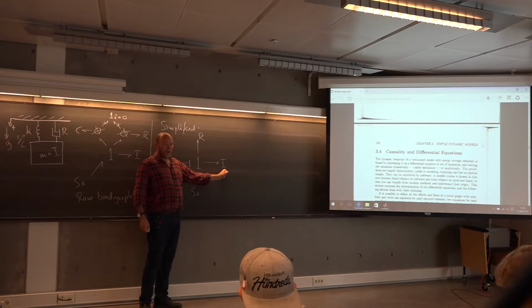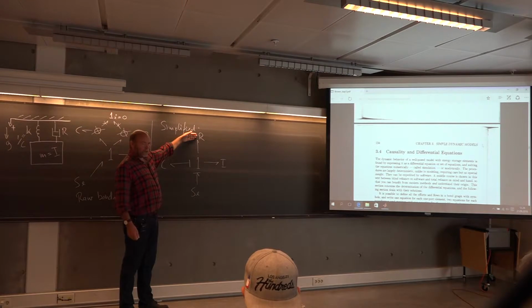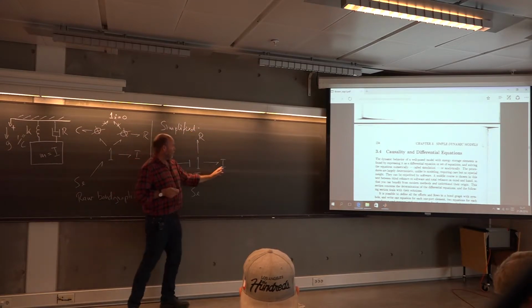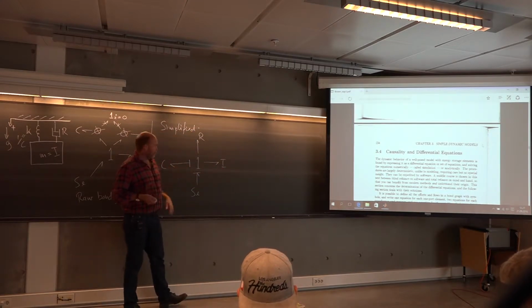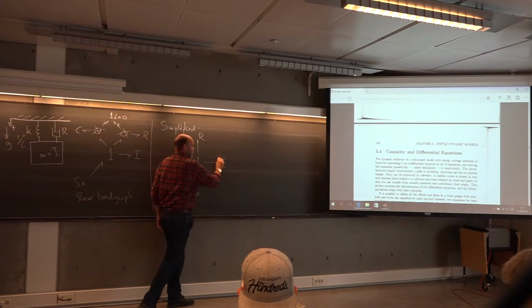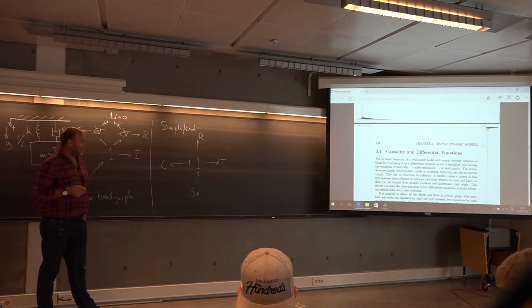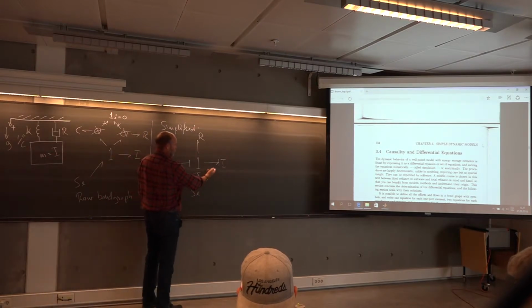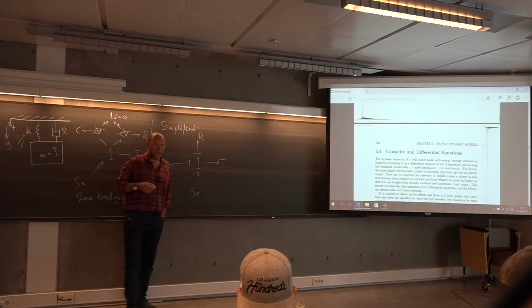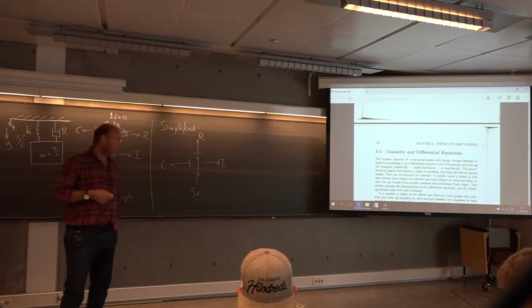Fortunately, I still have an I element, so I can still choose. For an R element, you are not allowed to choose. That's forbidden. So he should pop out automatically. But on a C and an I element, you can still choose. So here, of course, I also choose the integral causal stroke. That should be like this. Now I have found the 1 stroke away from the 1 junction, hence the last stroke has to be like that. So yes, this is a causal system.